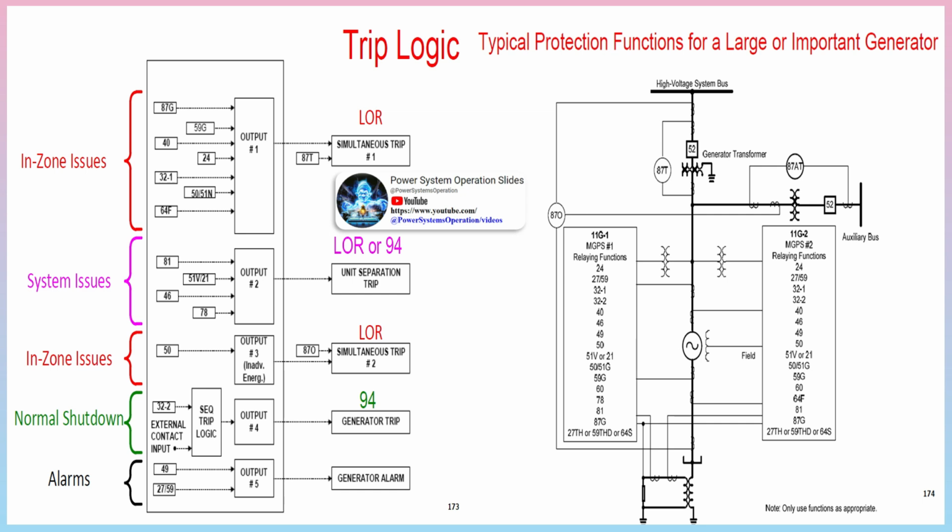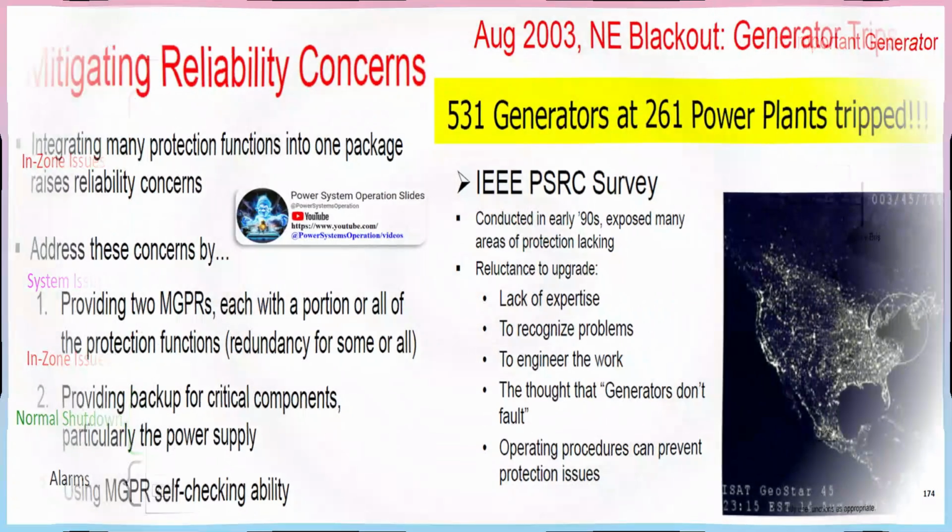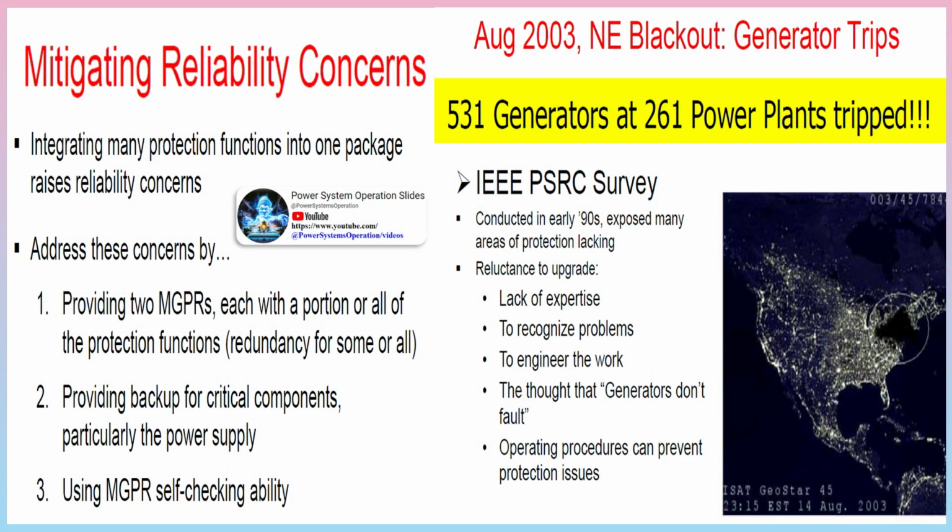Backup protection of generator. Backup protection should always be given in highly rated machines like synchronous generators or alternators. If faults that have occurred have not been cleared by the appropriate protection scheme, then backup protection relays should operate to clear the fault. Overcurrent relays are generally used for this purpose. Because the synchronous reactance of a modern machine is often greater than 100%, the sustained fault current fed from the machine into an external fault is invariably below the normal full load current.